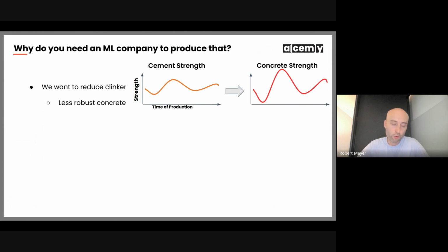So basically, if I order a low carbon cement that is supposed to have 50 megapascals compressive strength, then it should be very close to 50 and not have 55 or 45 megapascals, because again, that problem might get amplified later on in my concrete mix design.